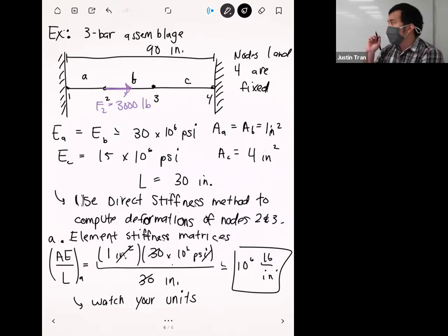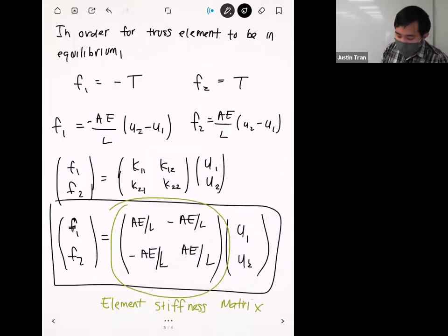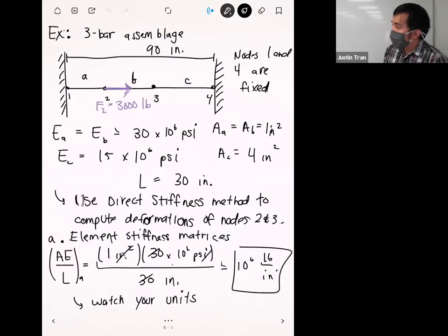Correct. So we'll do 1D and we'll introduce 2D a little bit today with truss and beams. But we're not going to go beyond that, because beyond that the math gets really crazy. There's another set of lecture notes after beams called frame equations, which are 2D elements, but the math for that gets really crazy. For these ones, they're not so bad because the element stiffness matrix is 2 by 2. But for the frame elements, the element stiffness matrices get to be 6 by 6.